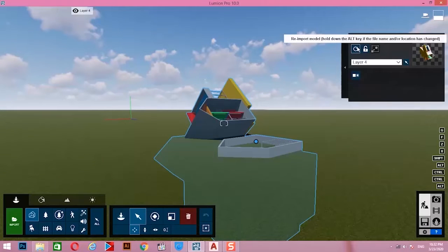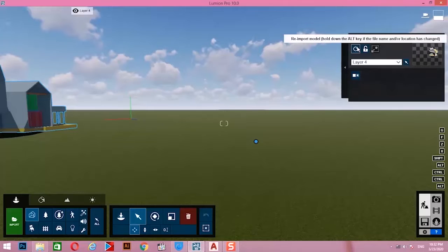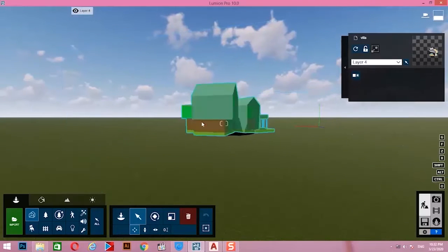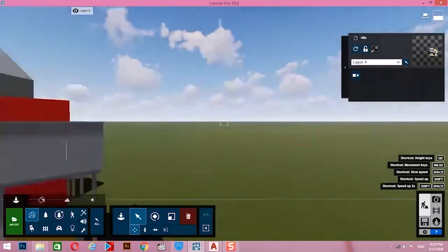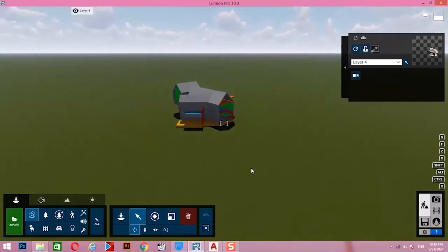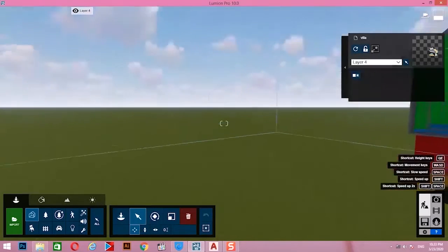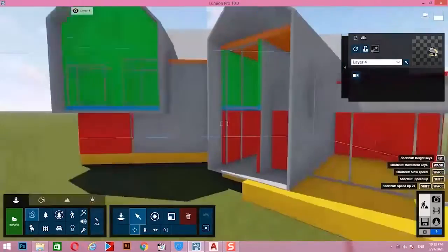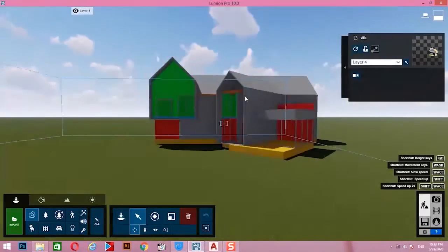So the object entered here, we select it. There is an option that says Reimport model. I just need to click it, and as you can see, the object got imported inside my environment very nicely. So the clamp for my object, as you can see, which is here, if you want this clamp to be specifically under your building, you should save your file and make it another file and place this on 0, 0 placement on your map, and re-import it again.